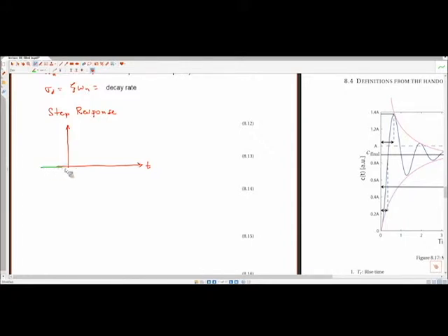All right, so if we have this step response, in the time domain this is R of t equal to A u of t. In the frequency domain, again for those of you who were not here on Wednesday, from now on we are going to be dropping the s term on all signals, assuming that we're working in the frequency domain. We're going to be working in the frequency domain so much that it's going to be the most common case. I forgot, my notes have this as A, not as A bar, so let me remove that bar there. R of s in this case is equal to A over s, if that is what a reference signal looks like.